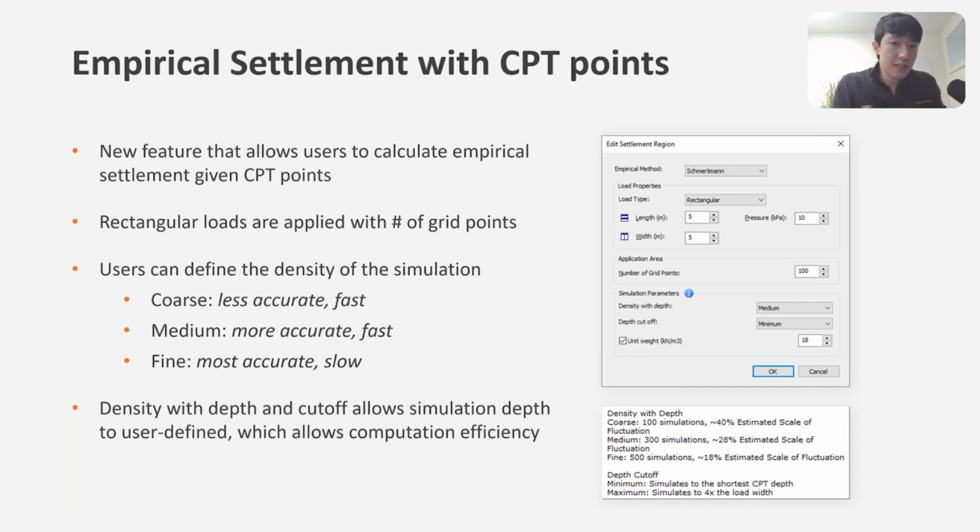This is a very useful tool because if you have the CPTs, you don't necessarily have to go through all the struggle of what we previously discussed about the CPT layering system with CPT points. All you have to do, as long as you have the CPTs, is see what my general overview soil profile is, given the CPTs for the defined region.